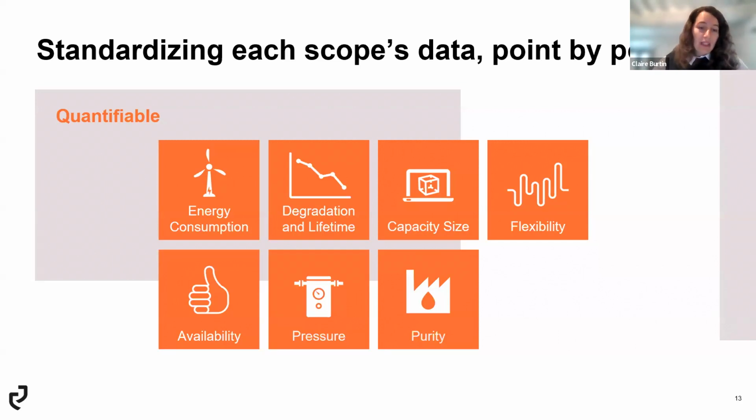Is it including energy losses due to the different connections between the items? Is it a value that is in AC or DC? Is the energy consumption data for 100% load of the electrolyzer, or is it for, I don't know, 60% load of the electrolyzer?